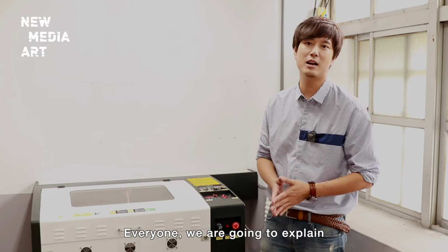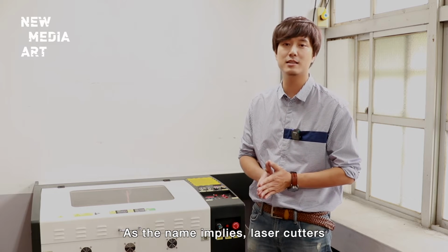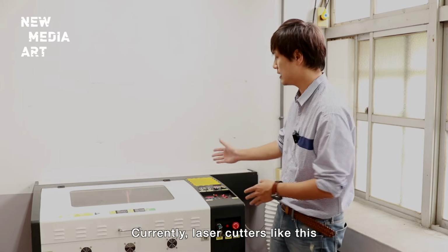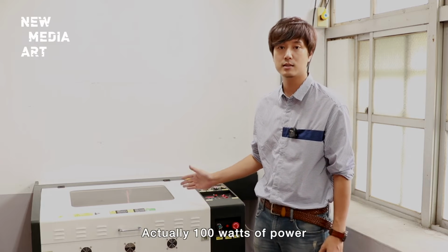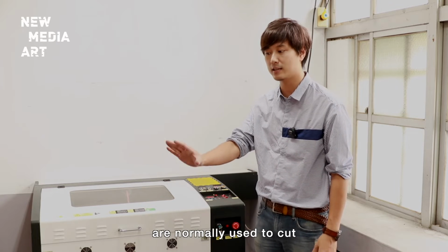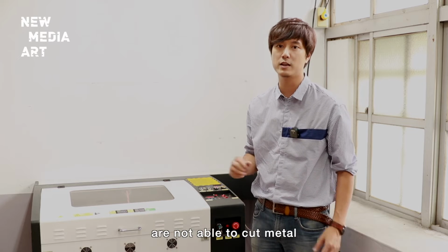Okay, everyone, we are going to explain this laser cutter. As the name implies, laser cutters use the power of light concentrated into a laser to cut sheets as we wish. Currently, laser cutters like this have a power rating of about 100 watts. Actually, 100 watts of power is already enough to cut thicker sheets. There wouldn't be any problem. Laser cutters are normally used to cut wood boards, acrylic boards, etc. Laser cutters are not able to cut metal.